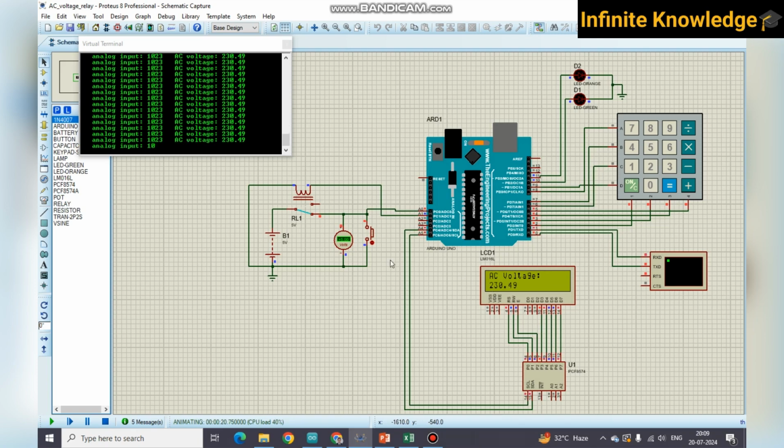Whenever I press this switch, it starts our input supply, and that's why you will get an under voltage tripping error, because the input voltage decreases. You can see that at an instant I am getting under voltage tripping. There are two relays: an orange relay which indicates the under voltage tripping, whereas a green relay glows when the over voltage tripping happens.